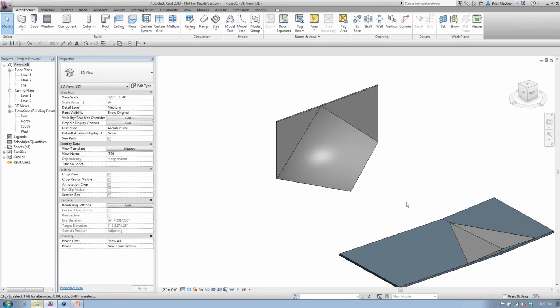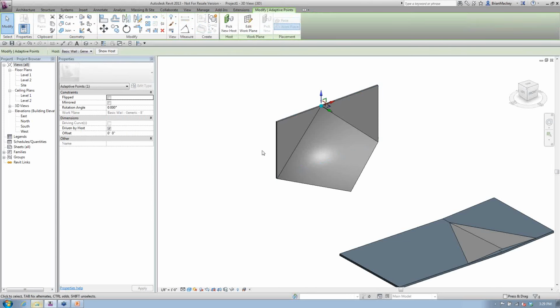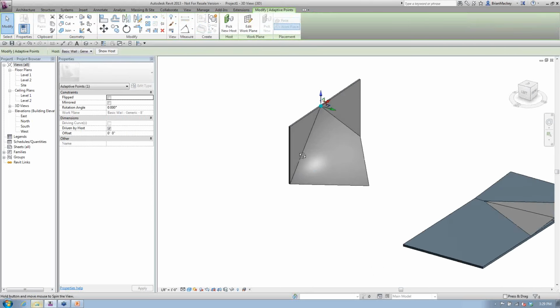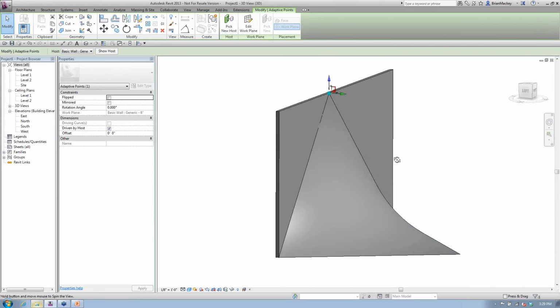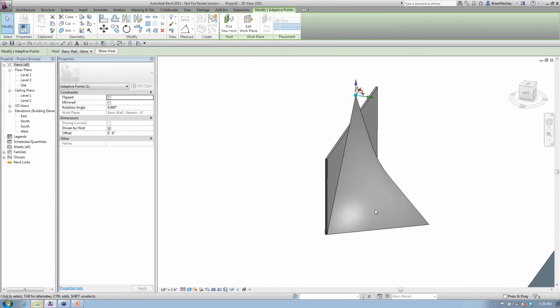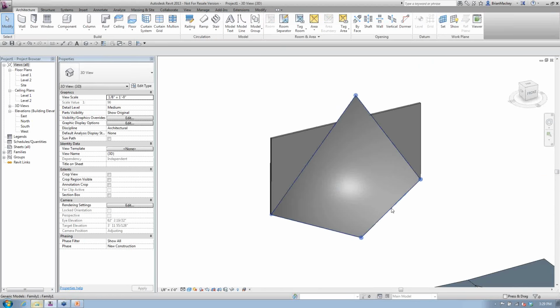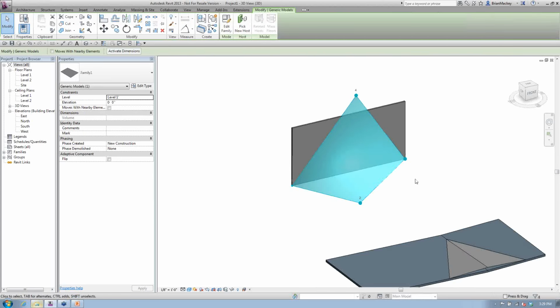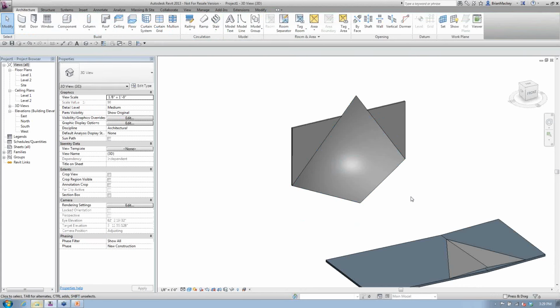You'll also see the same thing with the points here. If I look at the point here, since this point is hosted up on the wall, I must not have hosted it on the wall correctly, because I'm not getting the same properties I had for my other adaptive points. I knew I was having issues with that one when I placed it, because it's still allowing me to break what's going on there. Oh, I hosted it to the face of the wall, I think is what my problem was. Had I hosted that one correctly, I might have to go back and redo it, I would have had the same properties for those points, like segment length, as long as it's hosted to the object.